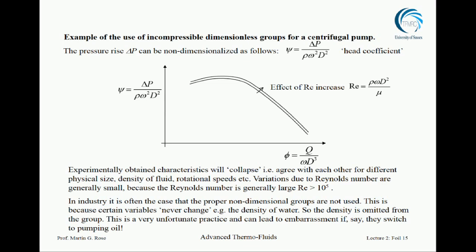now on a curve which has a positive gradient, which means that if the flow rate goes down, the pressure goes down, which makes the flow rate go down more. So the pump is unstable. It cannot pump stably on a positive characteristic.